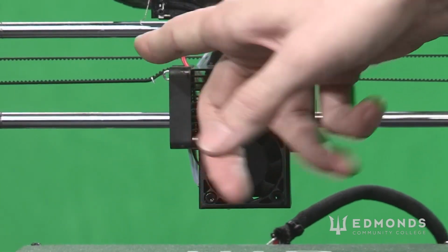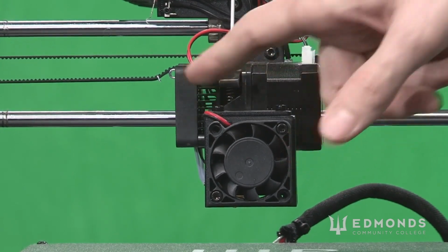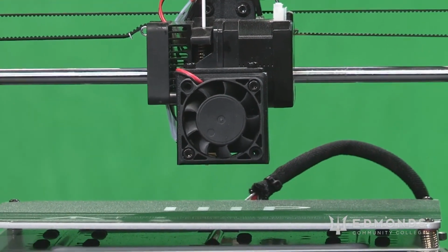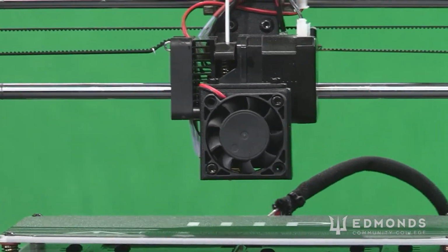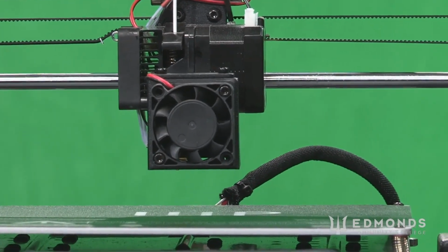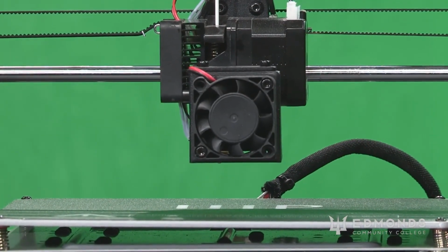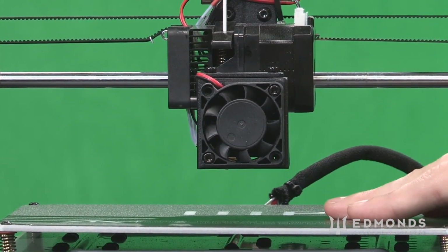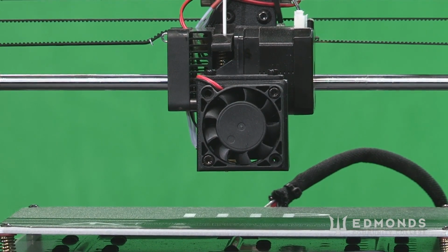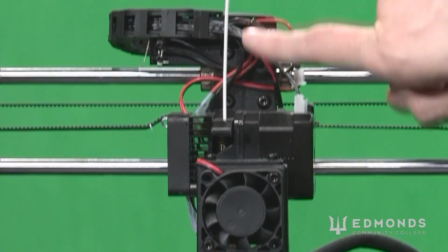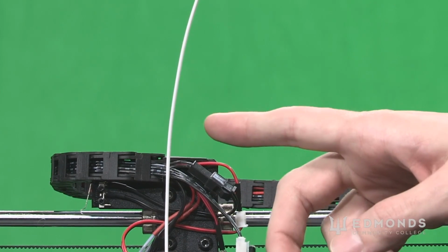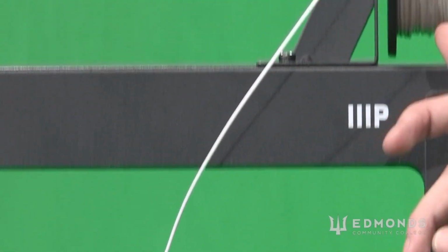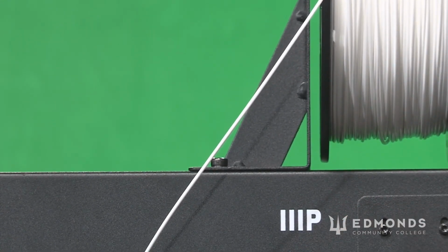We also have another case fan here, cooling vanes for the extruder assembly, and then down here we have a build plate. Also not to be underestimated, the chemical properties and surface properties of this build plate are very important. This one is heated so that we can maintain a sort of atmosphere temperature just above the plate, but also help adhere our material to it. And then our material itself is fed in through the top of the extruder. This we would call the filament, and in this case we're using polylactic acid, a thermoplast, which comes off of what we generally just call the spool up here.